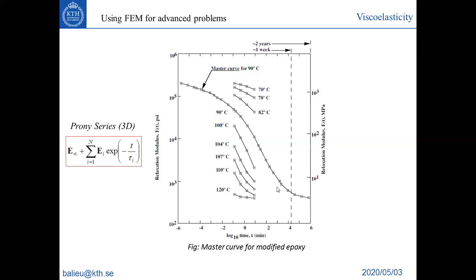And the other way, if you go here for the very long time, again, if you make this longer and longer, there is also a saturation here. And this is a very long-term behavior. So if you remember, this long-term behavior is this E infinity. So that means the long-term modulus here.